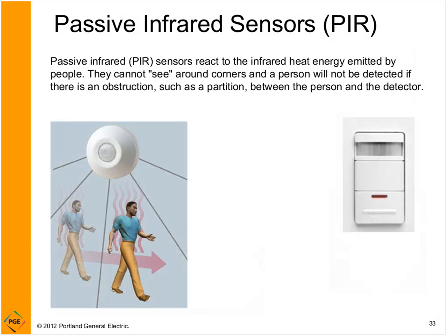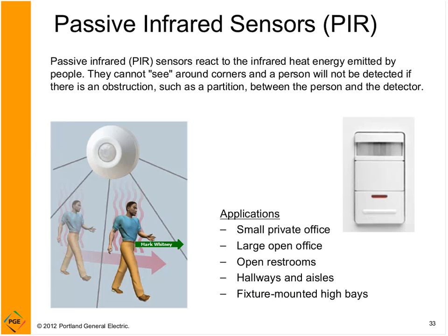And as I mentioned before, it can replace a simple switch, or it can be a ceiling sensor type of occupancy sensor. But because they don't see small movements, if you get further out, you can see that there's more distance between the infrared rays going out. So the further away you are, the more likely it is to turn off when you don't like it. So sometimes you have to do the big wave. But the passive infrared are the least expensive type of sensor.